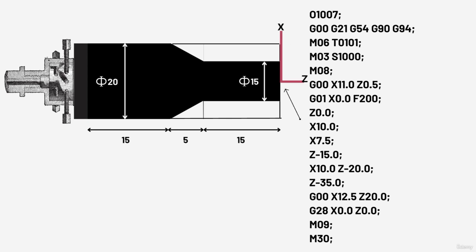So this point here is considered as datum and the tool will be moving from this point O to 1, to point number 3 and point number 4. Now we will write the corresponding workpiece position and X and Z coordinates in a table format so as to have a mathematical deduction prior to writing the program.